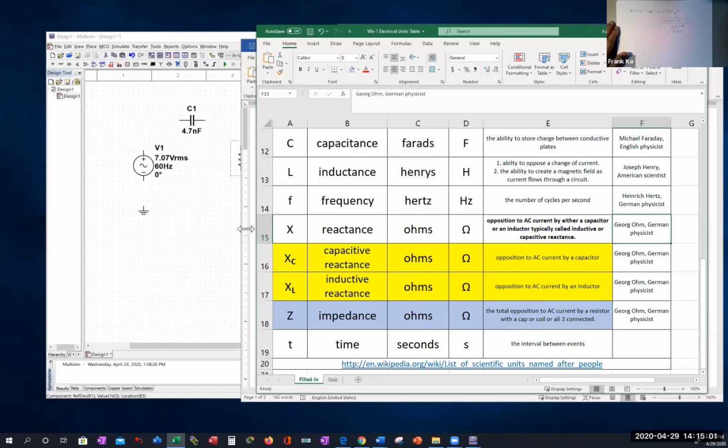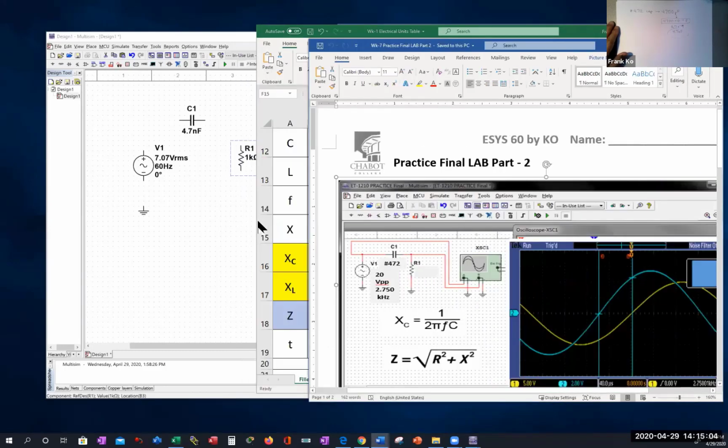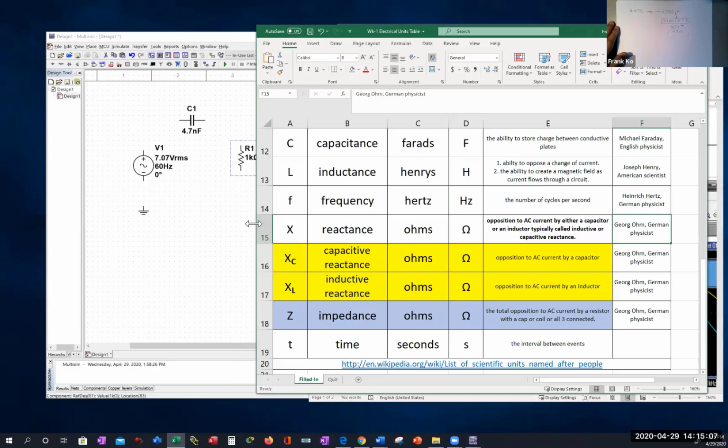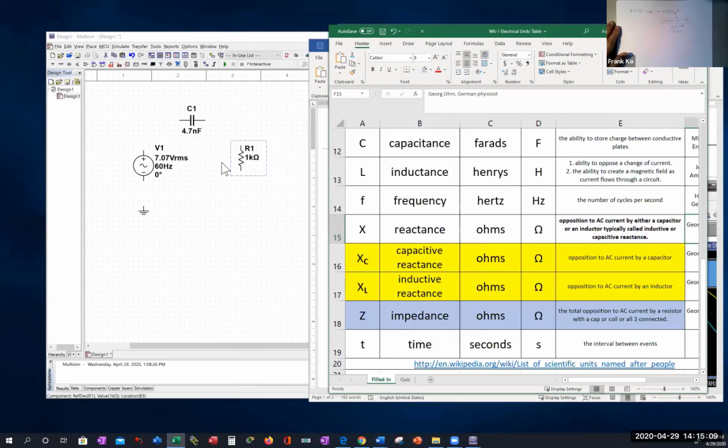If you look at the schematic that I have over here, do I have an AC source? Do I have a capacitor? Do I have a resistor? I'm going to connect these in a moment. And so the capacitor, this guy, is measured in what units? Nanofarads. We interpreted that based on the code that we were given, 472. In the presence of AC, it will exhibit a certain amount of ohms, which we can measure, which we can calculate, and then determine the effect of very, very quickly.